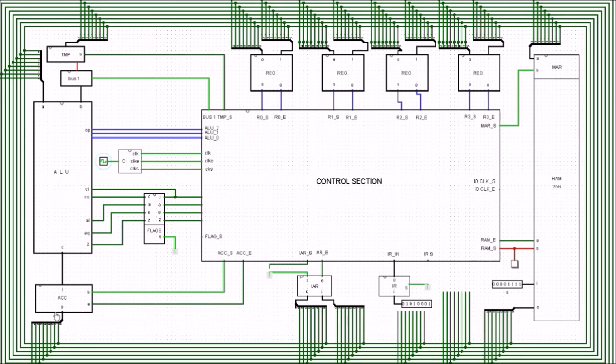So really, whenever we work through the next steps, the choice is going to be: do we load up the instruction address register with the address that's in this accumulator, or do we load up the instruction address register from the next byte within the RAM? And that's the choice we're just about to make.